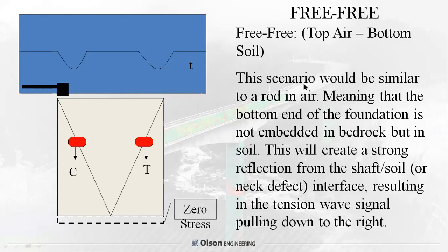A little bit of technical basis here. The echo you're looking for from a typical pile tip is called a free echo. In other words, when you hit at the top, your accelerometer, the pile cap moves down, and the accelerometer shows that. The echo goes to the bottom, moves down, comes back to the top, also in the downward direction, so your echo is downward.